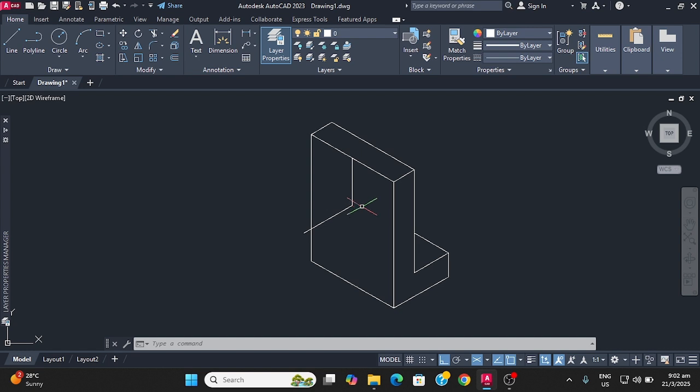So what we need to do first is change our plane, F5. We're using this one here, the left plane. So the ellipse command, EL, which is short for ellipse, and then I'm going to press enter. At the prompt here it says to specify the axis of the ellipse, or the arc, the center, or isocircle.